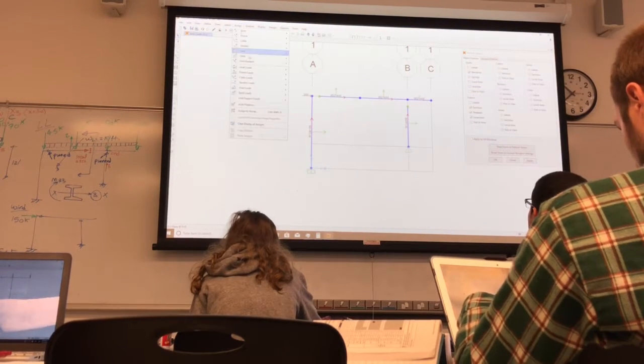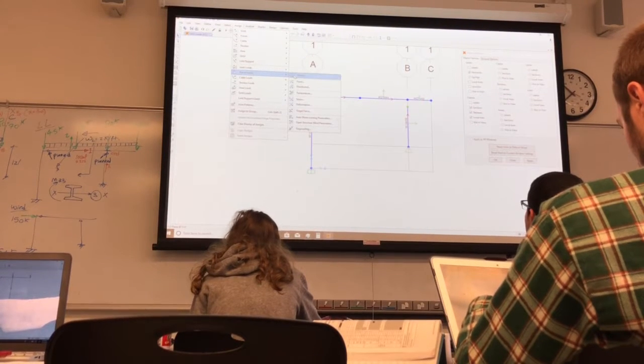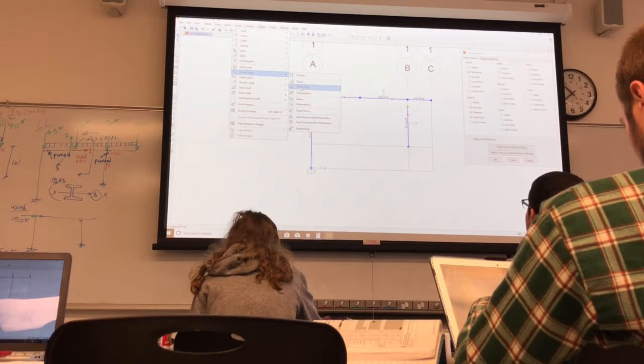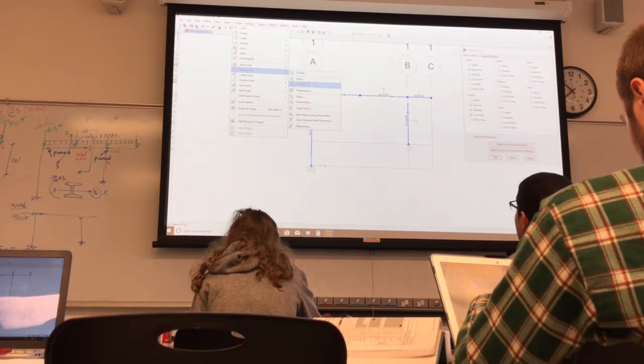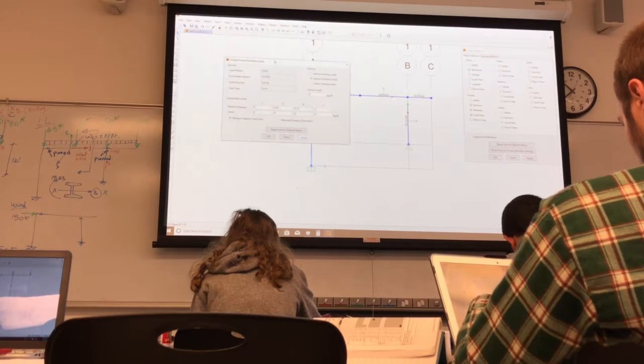So let's assign now. We assigned all the joint loads we have. We can assign frame loads now. We have gravity forces. I don't like to use the gravity one. I'll go to the distributed. It's the same, it gives you the same answer, but gravity is more confusing to deal with. So I go to the distributed load. But you can do the gravity, it's just, you know, you have to do a lot of changes.